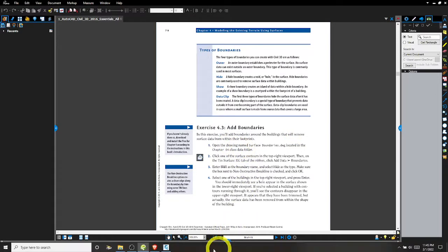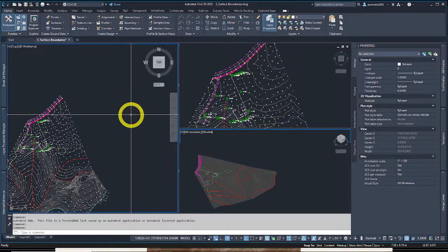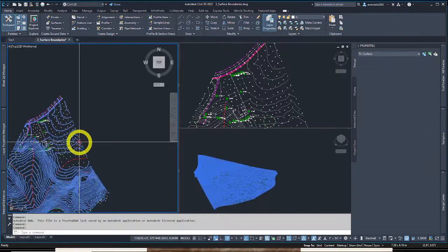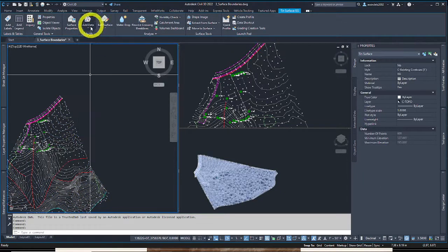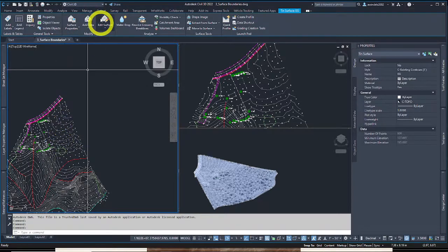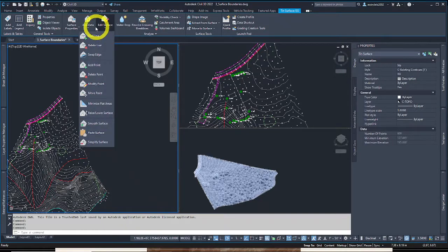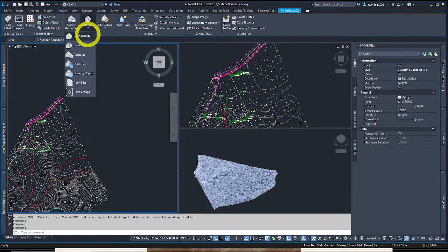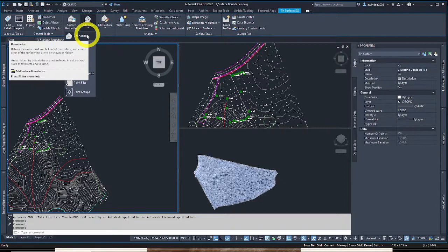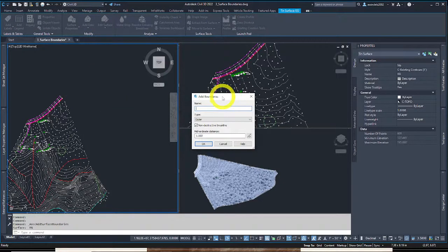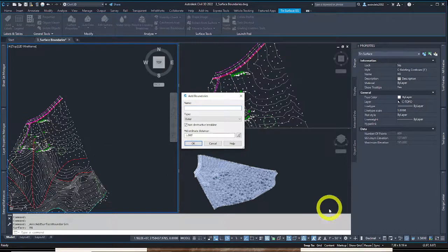We already have the surface open, or the DWG file open, and we're going to click on one of the surface contours to get started. And we have our options in the contextual ribbon with our TIN surface. We can edit surface data, but we're going to continue adding data. In this case, we're going to add a boundary. And it's going to come up. You can also pre-select the boundary and go to Toolspace and add them, but we did it this way.